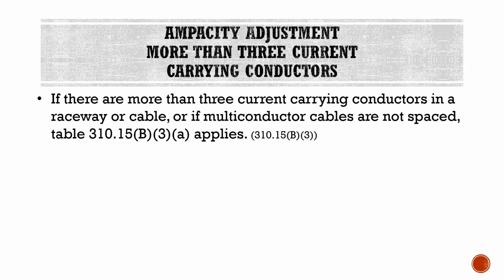Now the idea behind this is that if we have all these current carrying conductors bundled tightly together in the same area, whether it be inside a raceway or inside a cable, there's not going to be a lot of opportunity for heat dissipation.